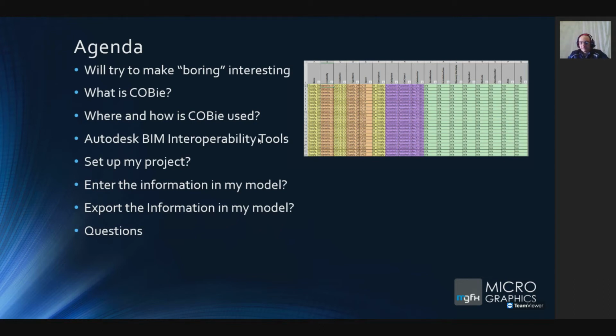We've looked already in one of the earlier webinars at applying the British standard or the American standard or any other standard or even a custom standard to a model. One of the comments that was made there was that COBie should be set up for the model. If COBie is a prerequisite for the model to have, then COBie must be set up first before the standards are applied, because some of those codes will go into COBie. All right. Just as background.